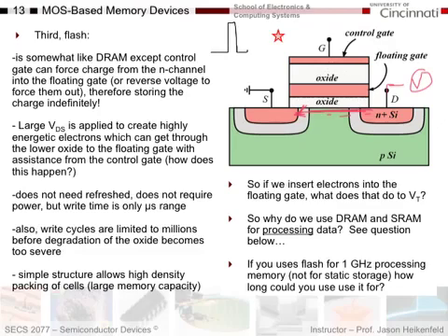One, the tunnel barrier can be thin and an electron could go through it, or the electron could get enough energy to go over the tunnel barrier. Well, this oxide here is like a tunnel barrier. If we use enough voltage across here to get the electrons accelerated to high energies, they will have enough energy to jump over this tunnel barrier and start charging up this floating gate here, which will then offset my external voltage and give me a different current value depending on if it's a 1 or a 0.